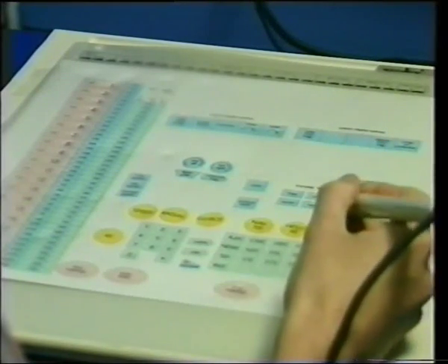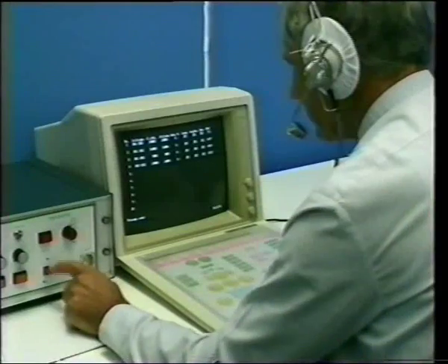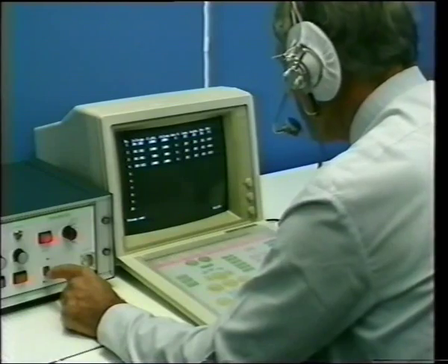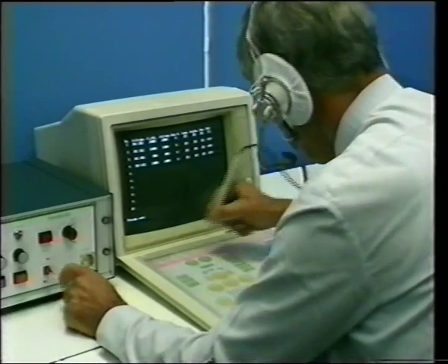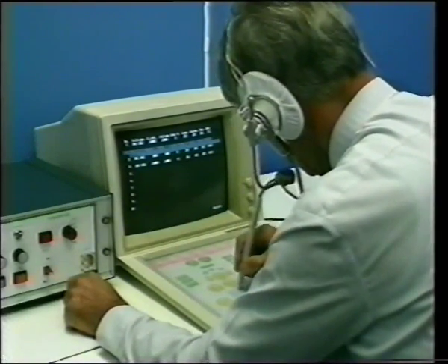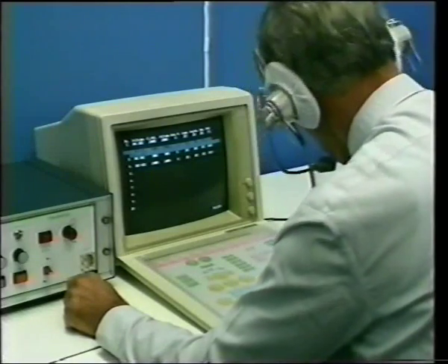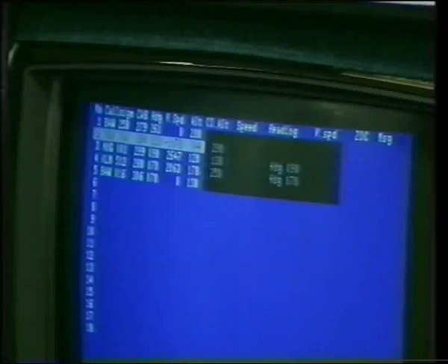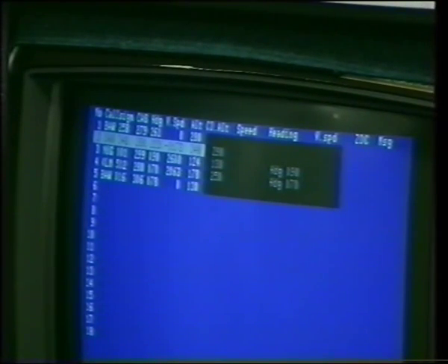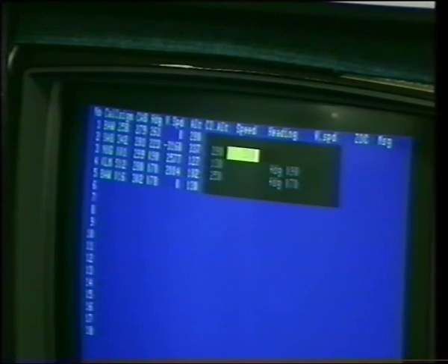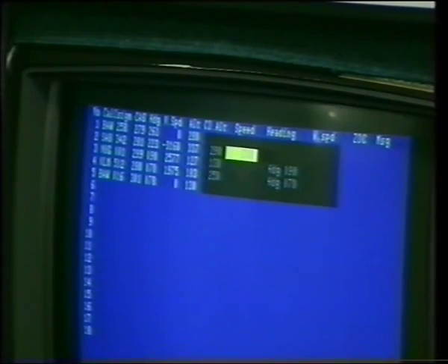In the experimental setup for the Mode S datalink demonstrations, the STAN system, besides constituting the ATC component of the datalink with the BAC 111, also provides additional simulated traffic with equivalent airborne equipment to present the controller with a realistic ATC environment. Instructions and acknowledgements are displayed on the EDD in exactly the same manner as our test aircraft.